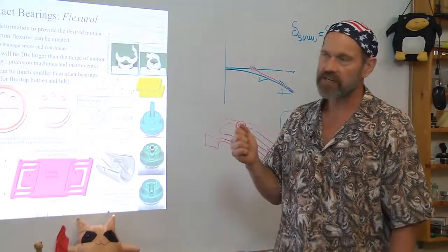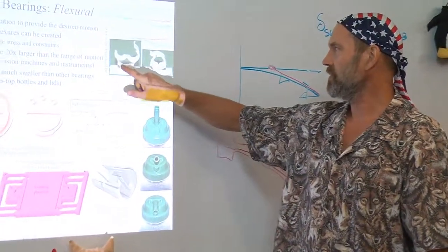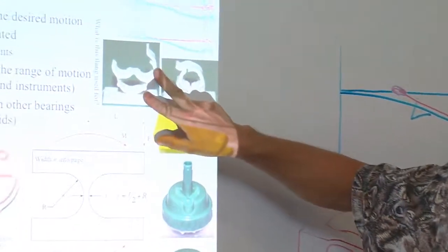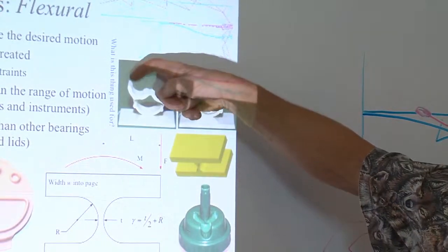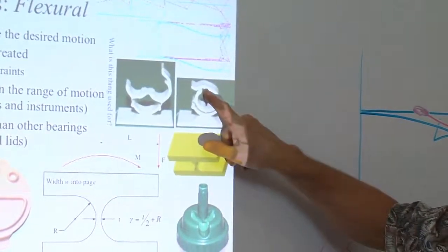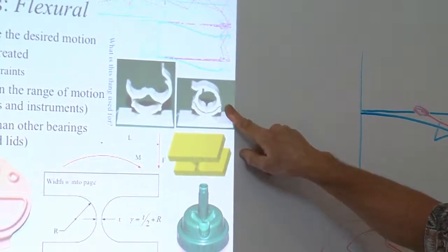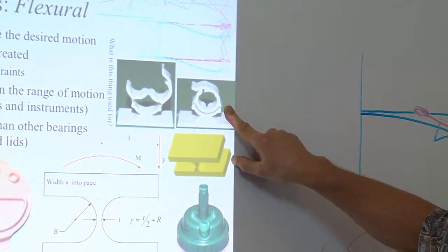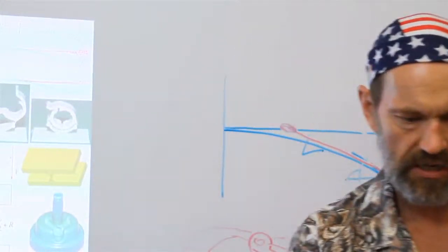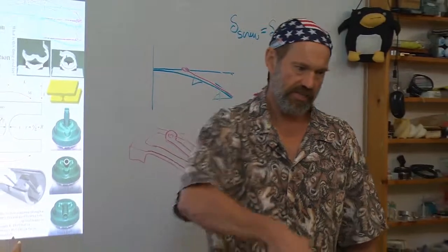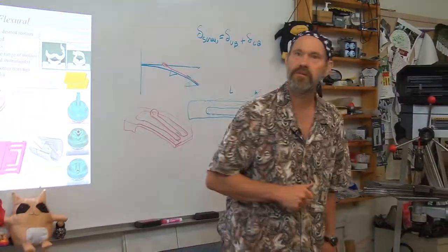The other thing to note about flexural bearings with respect to consumer products that you may design, and even industrial products: for example, here is a structure that's all injection molded. It clamps over and then snaps closed with a snap connect, and this is for holding cable bundles. So this structure, with these adhesive elements, you would adhere down on your machine, lay your cable bundles in it, and then just snap, snap, snap, snap.